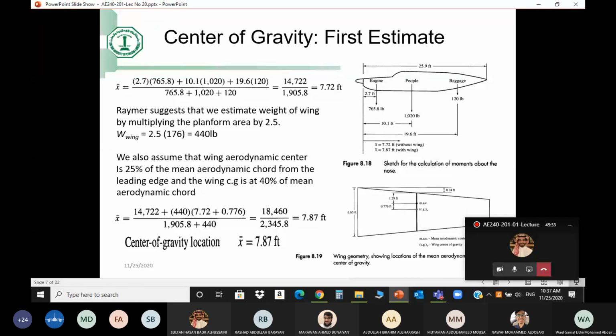So we calculate what's called the travel of the CG. The CG will travel between this point. Maybe the CG is here. It will go sometimes like this, or it will go like this, or like that, or like that. But it will be confined between 2 limits. We just check the stability between the 2 limits.